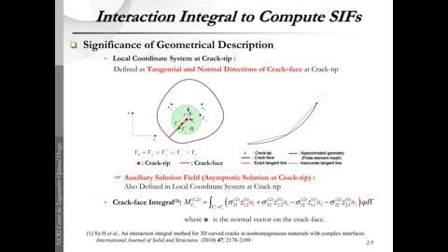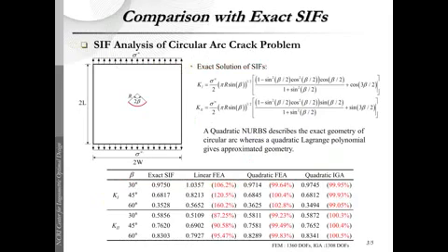Evaluation of the stress intensity factor using the FEM may lead to inaccurate results since the auxiliary solution field is inaccurately defined by approximated geometry. In curved crack problems, we consider the crack face integral in the interaction integral formulation. Also, the crack face integral includes the normal vector information on the crack face.